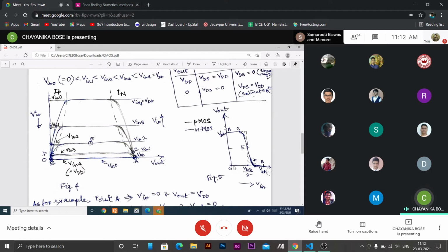Noise will be continuously varying. So if our original input voltage is 0, but some unwanted signal, noise, appearing in the input line gets mixed with this input voltage, then to the circuit the input voltage, originally 0 volt, appears as 4 volt. So V out will remain fixed at 10 volt still.